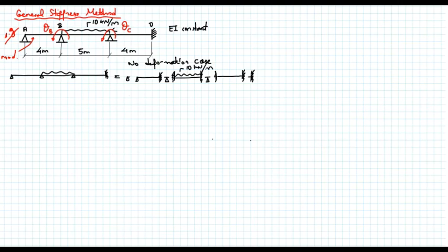So when we calculate the fixed end moments, this is equal to 20.83, and this one is equal to 20.83. And the shear forces, we don't use them, but let's calculate them. This one is 25, and this one is also equal to 25. So this is the case when all nodes are clamped, all the degrees of freedom are equal to 0.